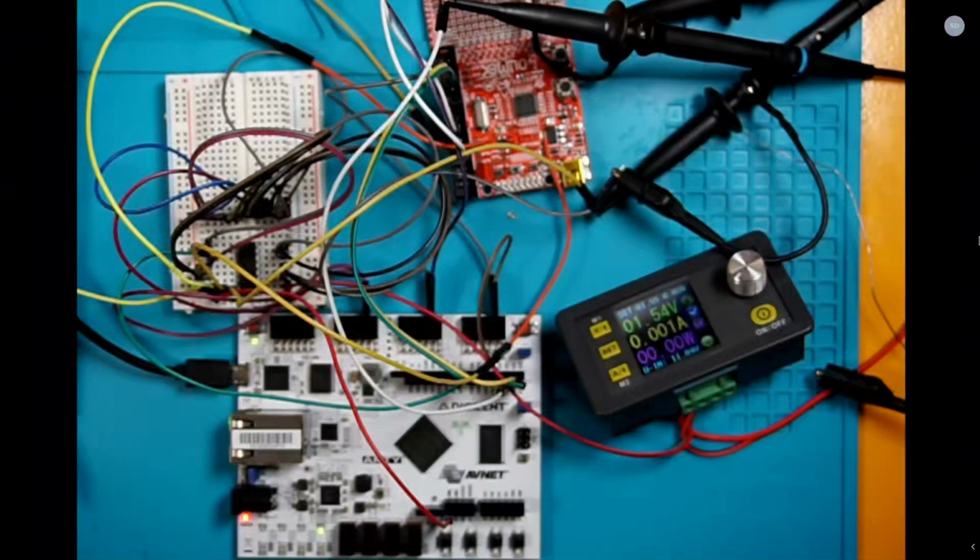So moreover, in our case, the microcontroller board actually has an additional feature: because it uses UU encoding, you'll see that there's no binary data that falls into essentially valid encoding. So what that means is you can send data directly through the FPGA as long as it has a non-printable byte in front of it, and then you can process these special bytes to issue commands to the FPGA to basically tell the state machine, hey, this is a configuration. The next 2 or 3 bytes are configuration bytes. Take that configuration, load them into the registers of the state machine, and basically have at it.